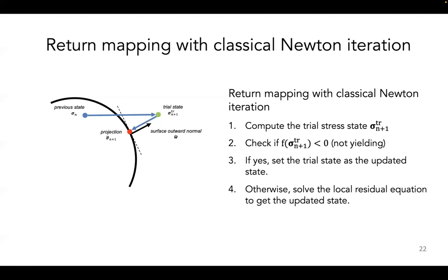Now, this is for perfect plasticity, it's easy because the yield surface is already fixed, and then you just shoot it up and then go down, okay? But when you have hardening and softening, this thing is dynamic, so when you're shooting it out, you need to figure out how much the yield surface needs to move, and then you also need to match them, okay? You need to kind of have a kiss between that stress state and the yield surface.